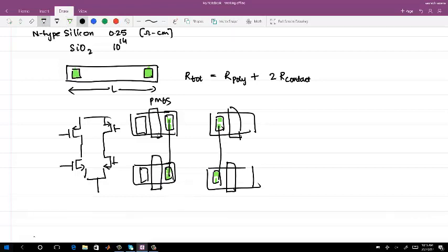Now if I change the number of contacts on the two sides, then you will see a different DC operating point. Even if there is no process variation with the MOSFETs or anything, you change the number of contacts on one side with respect to the other. So if I actually go and put another contact in the path, then I will see a different DC operating point.